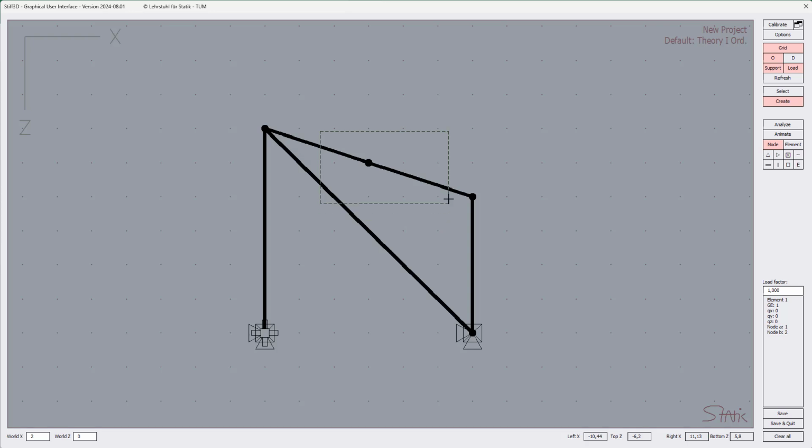And if we would like to put these elements back into one, that's exactly this merging option. So we select all these elements which we would like to merge into one, and also the intermediate nodes here. After having done that, we go with the mouse to one of these elements, right mouse, and we go into merge. And you see, we have received back our one element.